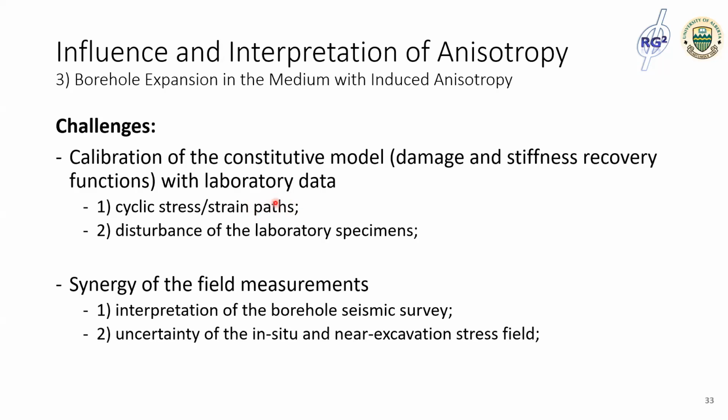And the other independent field measurements, for example, the borehole seismic survey, are also useful in informing the initial condition of the test, and the uncertainty of the in-situ and near-excavation stress field may be reduced by performing more in-situ stress measurements associated with the stress modeling around the excavation.